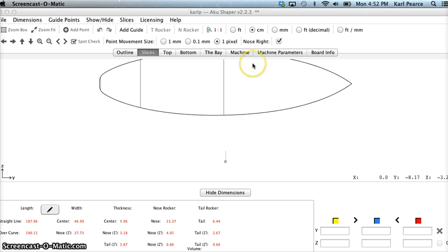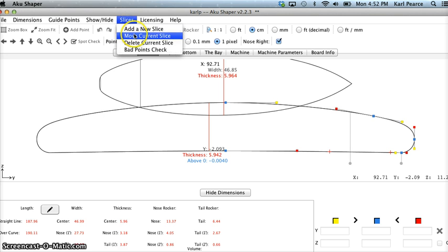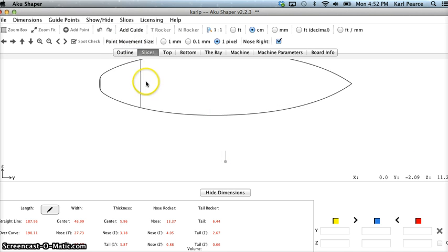That should be fine if you're making a longboard type skateboard, but if you're making a shorter board, we will need to further remove the middle slice. Otherwise the computer won't be able to calculate the shape. So, interesting to know, we've got feet, centimeters and millimeters. If you wanted to change all these, it's probably easier to work with centimeters on something of this scale.